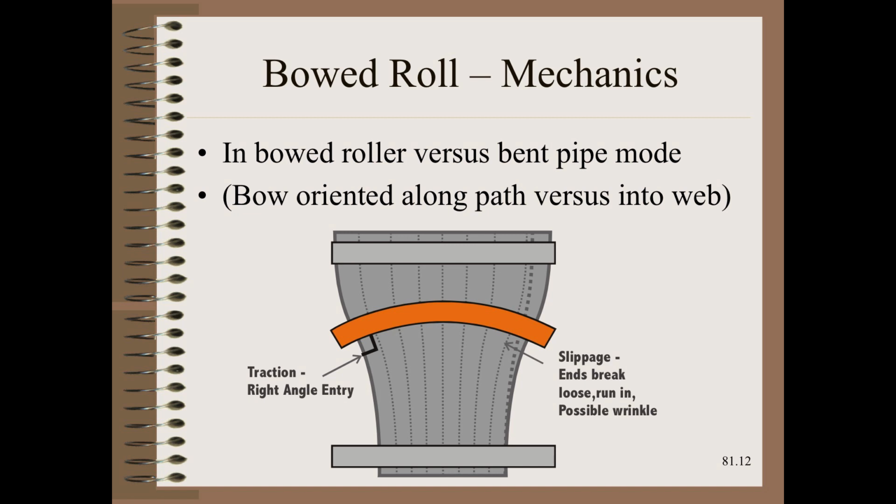However, the very edges are not usually where the biggest application problems are found. Rather, it is where the sliding outer portions meet the still tracking center. This results in what we sometimes call quarter-point spreading problems. This is easiest to see when trying to spread lanes after a slitter. The gaps in the lanes near the middle are large. On the other hand, the gaps between the end lanes may be non-existent. However, the quarter points don't just have no gap, they may be overlapped.